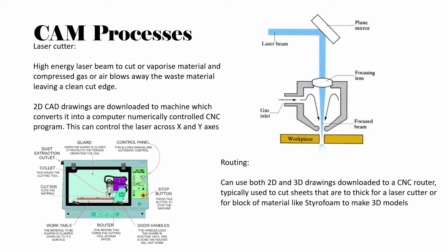So you have CNC mills. You'd have what looks like a drill bit, but it's actually a cutter. It will cut through material essentially how the laser cutter would, but then you've got to take into consideration the thickness of the cutter and that type of thing. It also lets you cut thicker material, so you can do timbers.